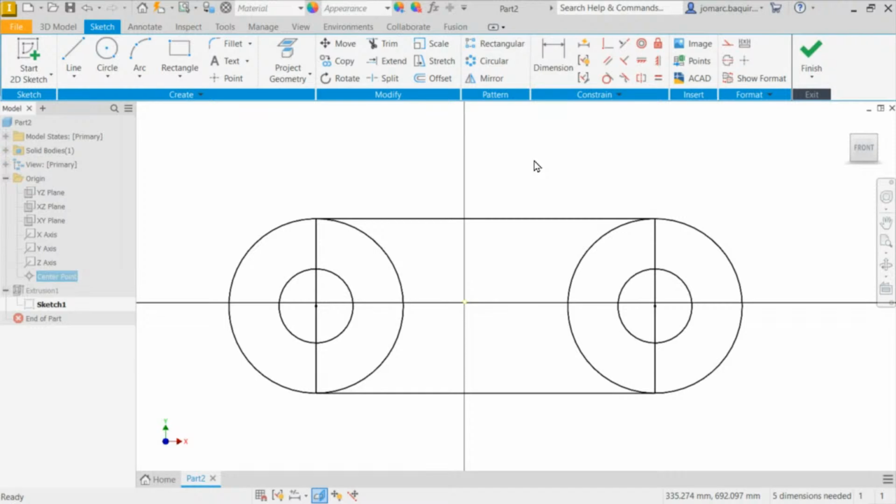By default I want you to think that the geometric center and the origin are preferably both coincident. Of course, in preparation for things like if I want to mirror this on the other side, I have this center or our plane to be used to mirror this, right? Instead of creating a new line as a mirror reference, by default, let's utilize the existing ones.